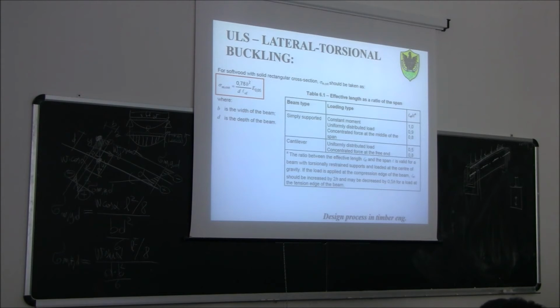Well, we need to think about how this beam is going to deform if lateral torsional buckling occurs. We said that this beam is going to deflect laterally and to rotate torsionally. Now, having a load which is applied here instead of here, does it make things worse or better? Worse. Why? Because it increases the torque moment applied to the beam.